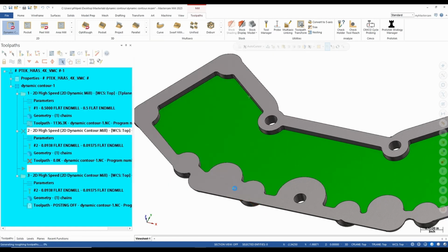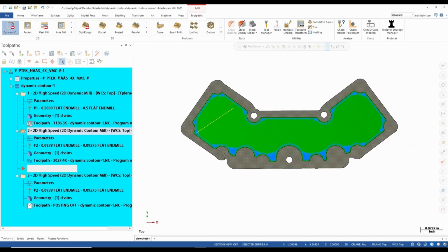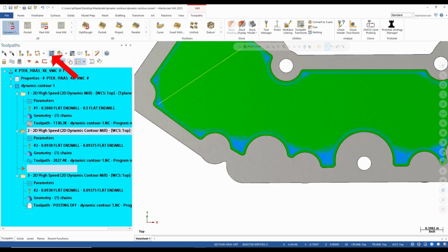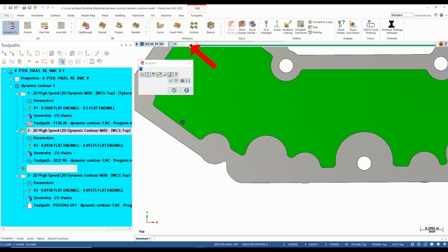So we're going to get a pretty quick generation of a tool path here. And one thing we're going to notice is my blue center lines of cut are pretty much just where there was material left over. And as we looked at previously, where the green areas were next to the orange, that's all material that Mastercam has to process to cut out of there dynamically and to give me a nice even finish when I go around this part. So if we go ahead and backplot this, I'm going to slow this down. We're going to start to see that great Mastercam dynamic motion that everybody should be utilizing for tool wear, maintaining chip load, and efficiency in the tool path.